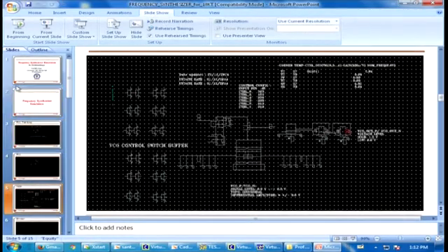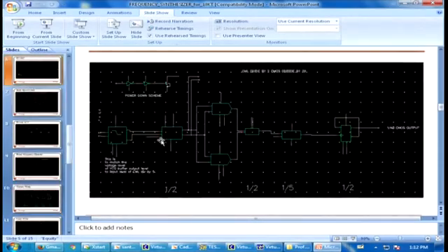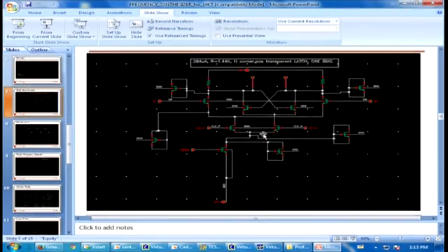And these are the switches for capacitor tuning capacitance. And this is the PFD. This is total divided by 40. So it's divided by 2 here, divided by 2 here, divided by 5 here, divided by 2. So total it's divided by 40. And this is a high speed latch. Okay, for division by 2 you are using. Yeah.